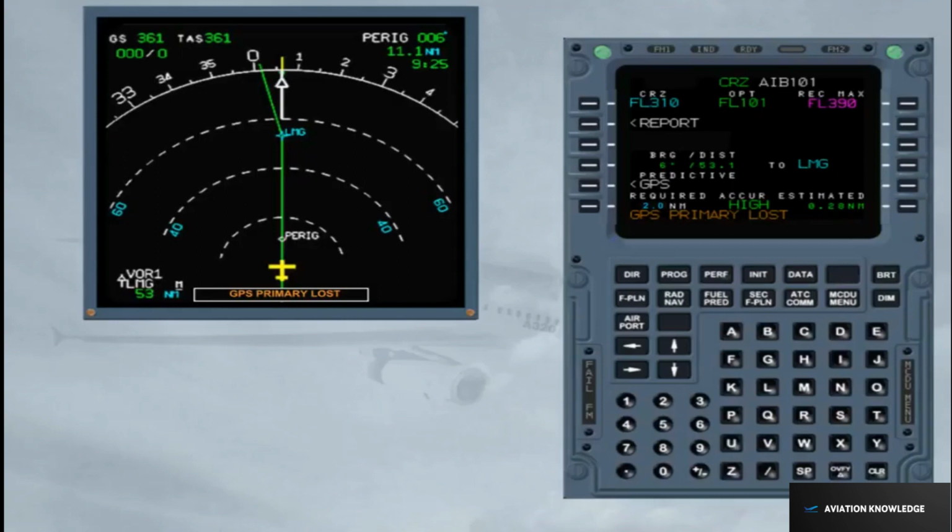Rules regarding FM navigation and flight planning. Rule 1. Cross-check the FM navigation accuracy. The FM position accuracy is essential for the proper functioning and validity of all FMS functions. Thus, cross-check FM position accuracy periodically, except when GPS is primary.